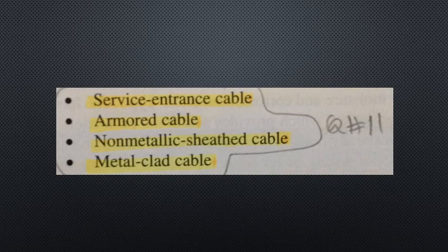Cable consists of several conductors wrapped by a flexible outer covering. Raceways are enclosures installed between equipment or devices that are to be connected by conductors. The conductors or cables are placed inside the raceway, which protects and supports the wiring. Unlike raceways, cable trays are not enclosed. They are simply trays on which cables are laid.